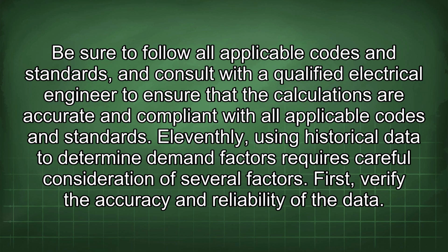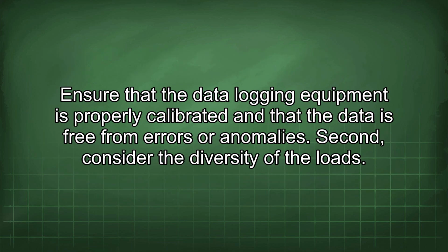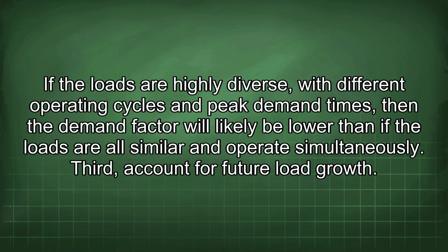11thly, using historical data to determine demand factors requires careful consideration of several factors. First, verify the accuracy and reliability of the data. Ensure that the data logging equipment is properly calibrated and that the data is free from errors or anomalies. Second, consider the diversity of the loads. If the loads are highly diverse with different operating cycles and peak demand times, then the demand factor will likely be lower than if the loads are all similar and operate simultaneously.